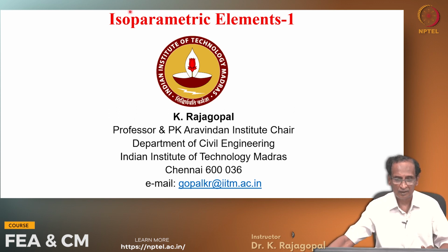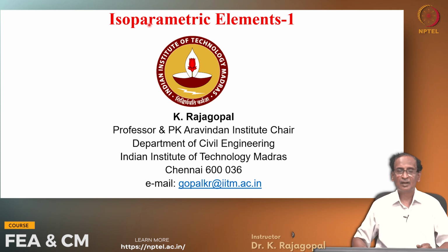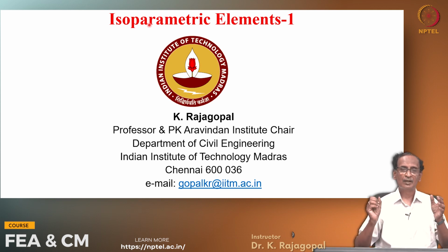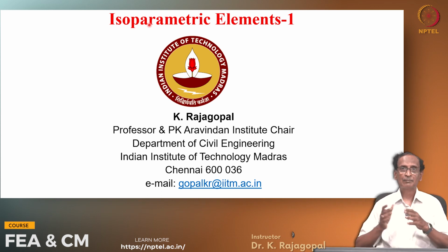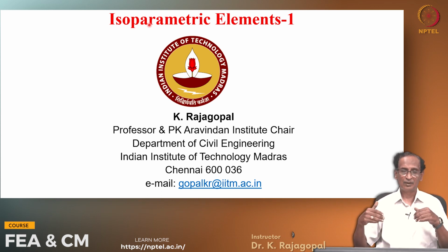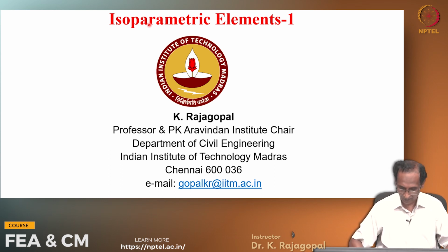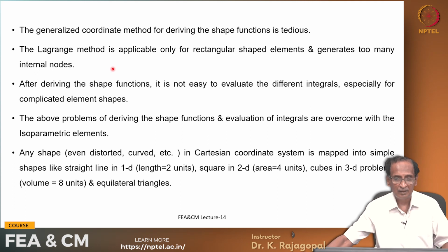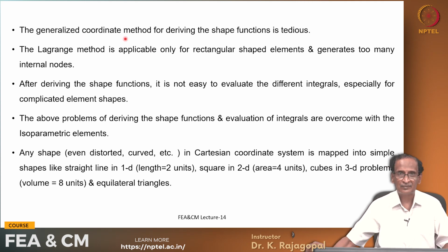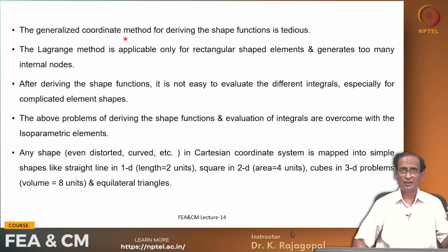finite elements which are called isoparametric elements, that give us an advantage that whatever may be the type of element, we can do the integration and we can control the accuracy of our integration. Either we can get the exact value or slightly under predict our integral value. And so the need for this is felt because our generalized coordinate method for deriving the shape functions has resulted